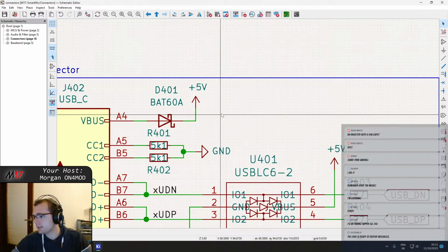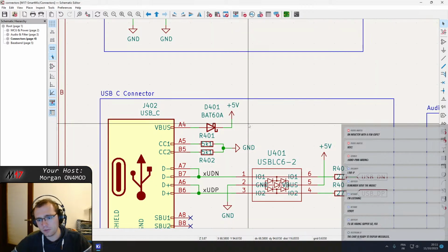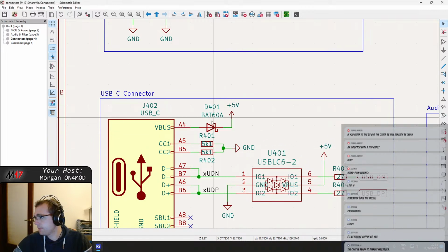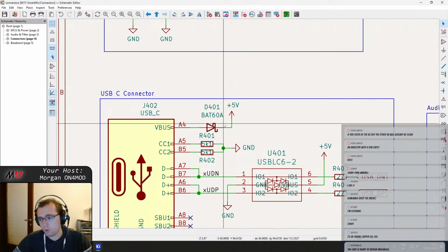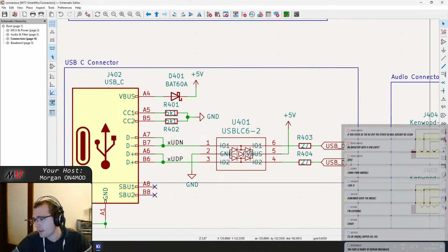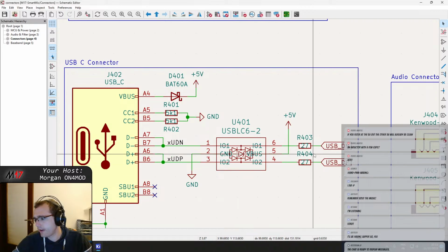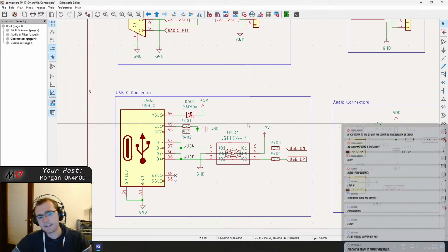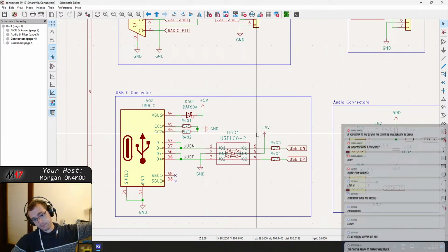So, okay, I think we do need a few ferrite beads on the board. It's never going to hurt, but we need to place them at specific places. I think one should be needed here, between the computer and the board. If you filter the 5V output, the other 5V will already be clean. Yes, that's true.